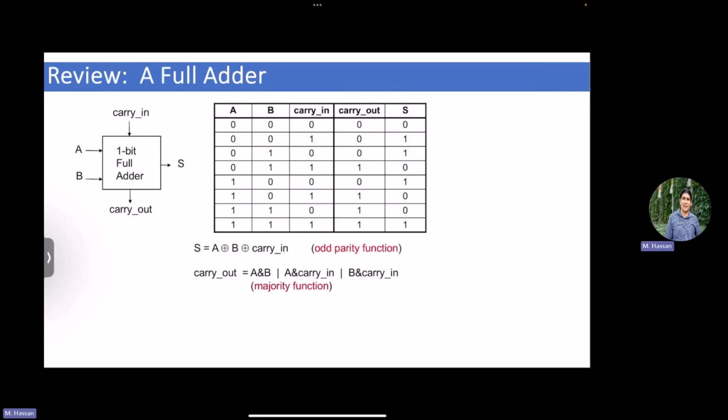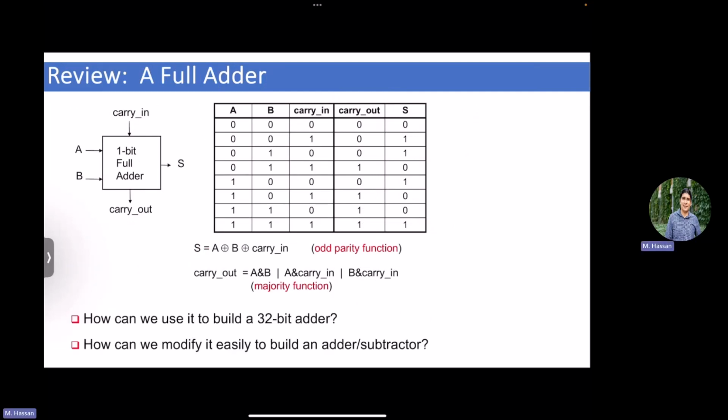And then the ALU is composed of one-bit full adders, and then you concatenate them to create different types of adders. There's the ripple carry adder, there's the carry forward adder. There are multiple types of adders that are usually covered in either digital design or arithmetic courses. We don't need much of this right now because this is a lower level computer organization. But what we need to understand is that behind this block called the ALU, it's composed of sub blocks. If you remember lecture 0, assembly, multiple multiplexers, gates that compose circuitry, and at the end it will go to the transistor.